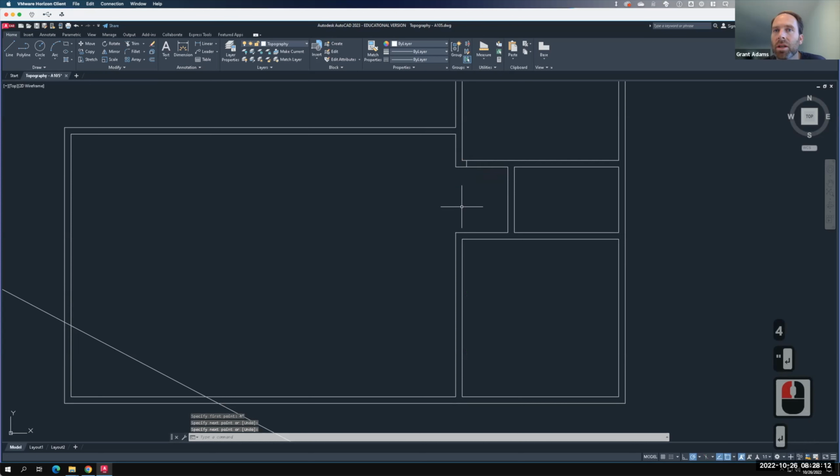Remember, that was just using my smart tracking. So I hover over this corner. I move the mouse to the right. I type 4 inches. And now I've created that line right there. And then I could offset this. So let's go to offset. My distance would be 3 feet this time. And we can offset, whoops. I did not.